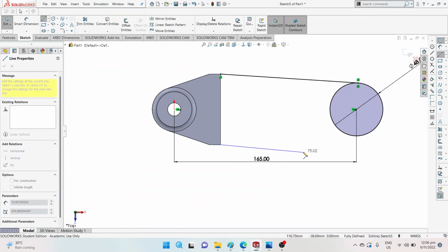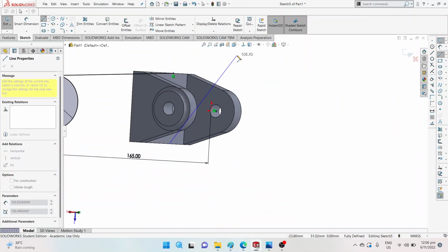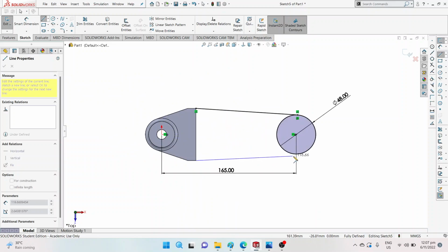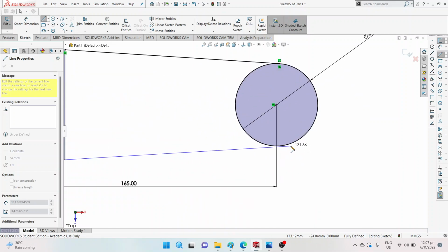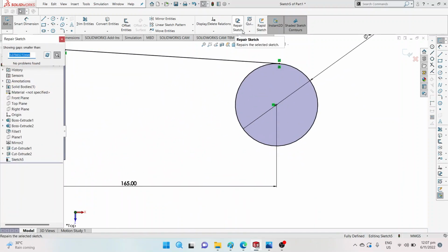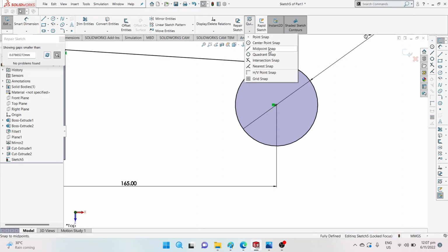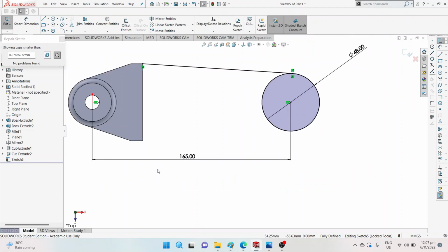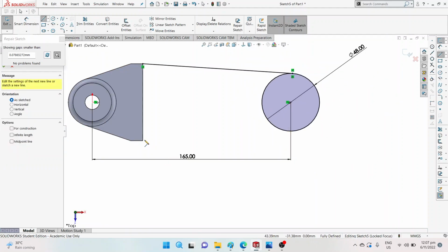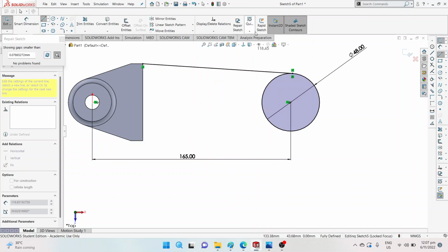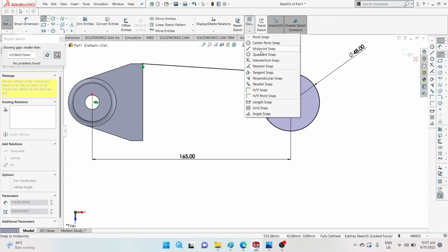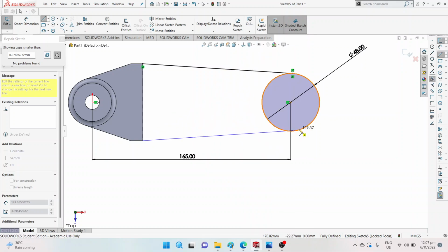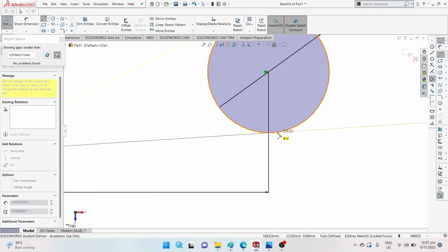And we make sure that it is snapped as well again. This is the quick snap to the tangent of the circle. Where is my tangent? Snap point, grid point. The point is missing. Oh, because the line is not drawn yet. I think it went escape. So here, this line, and then I need to select tangent snap, and the tangent point is somewhere here.